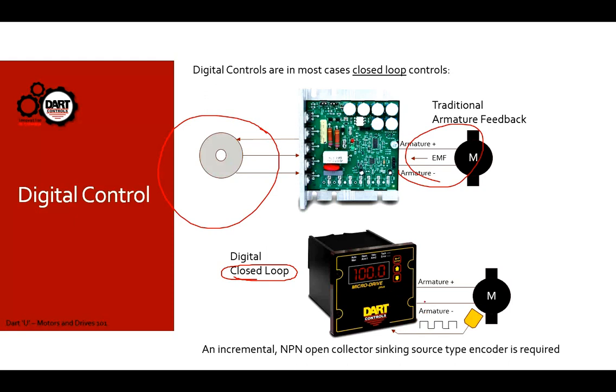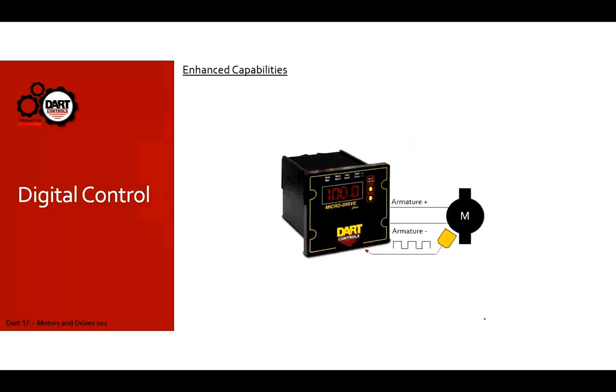automatically making motor speed changes under load conditions, environmental conditions, whatever it is that may be causing that motor speed to change. The encoder tells the drive, tells the control exactly how fast that motor is going in a different way, and we have a much larger range of response to the motor. The control will actually go to full output if it needs to get that motor to run the proper speed. In fact, one of the classic troubleshooting points of if the motor's running full speed only is, hey, for some reason I'm not getting any encoder feedback to the control.